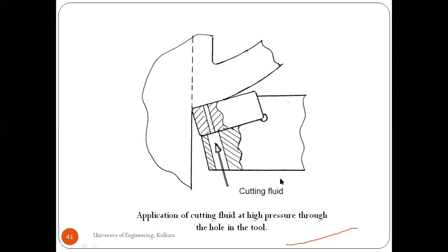So the application of the cutting fluid at a high pressure through the slot we have made in the tool, proper cooling can be performed, right?